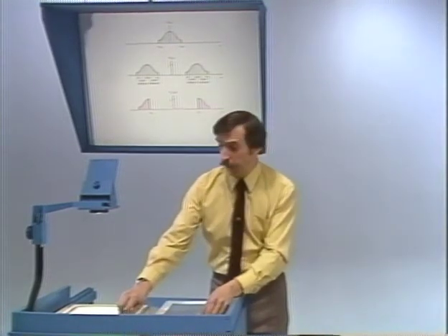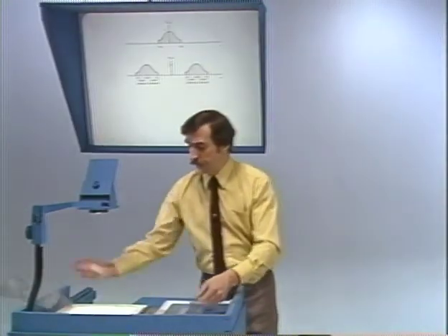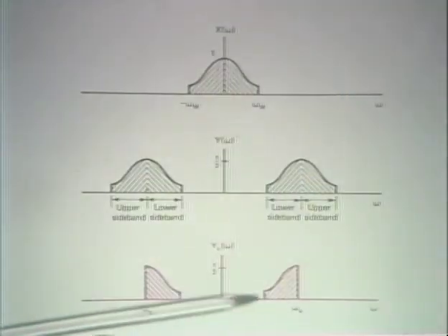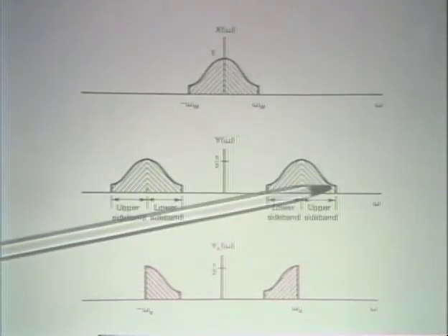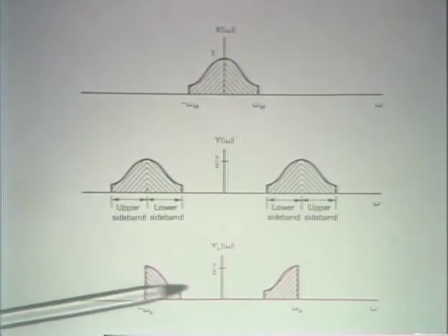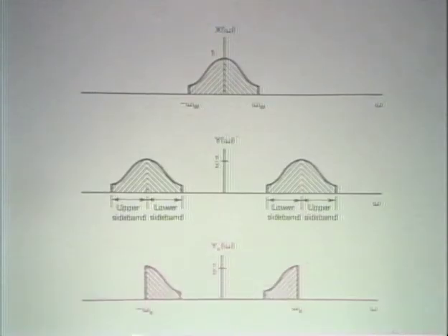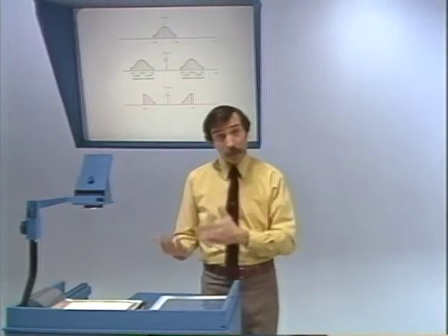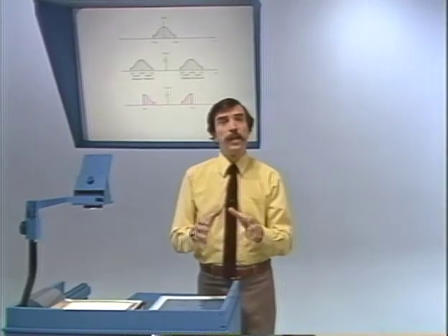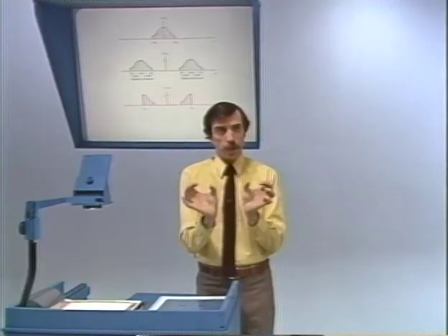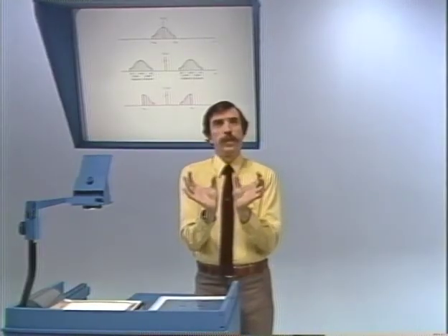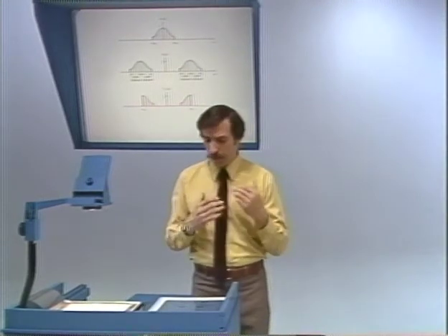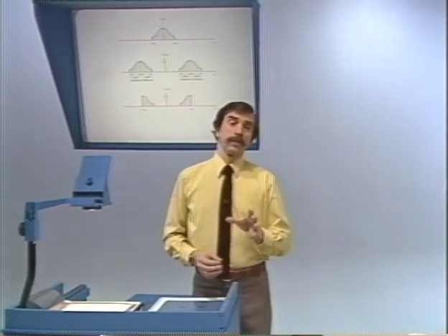What we've done is we've kept the upper sideband in this particular case. We could alternatively, by the way, think of putting this system together where we retain the lower sideband instead of the upper sideband. And in either case, what we've removed is an inefficiency in transmission of the signal. Namely, we have a real valued signal, but it only requires as much total bandwidth, in terms of the frequencies in which there's energy present, as the original signal.